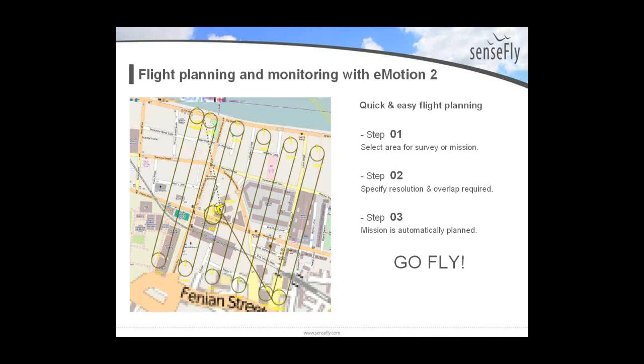The pitot, there's a little thing, it'll turn blue, and then it'll start blinking green. When it starts blinking green, that means the engine RPMs have cranked up. You tilt it at about a 10-degree angle, and the pitot on the eBee will turn green saying it's ready for flight, and then you just take a step forward, thrust your hands forward and release the eBee, and it's off and flying.